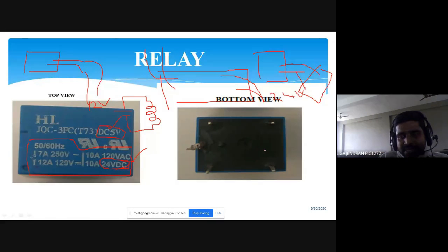Inside the stabilizer you have voltage regulator components as well as one timer circuit. After some time delay only, we will give the output to the appliances. That is for a production-relevant issue. Whenever power comes, immediately there will be high voltage. If you turn on your appliance with a high voltage, your appliance will get damaged.